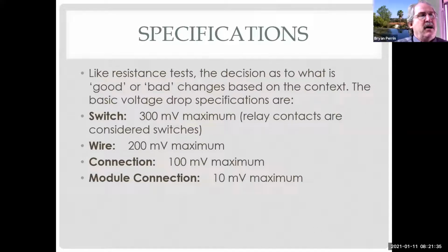But you can see it's not uncommon that, by the time I go through some connectors, go to my ignition switch and go down to my starter, I might lose 0.7 of a volt. Because, right, it's cumulative. I got wires, I got connectors, I got all these things. So even if I have an ignition switch that might be a little over, maybe my wires and connectors are under. So the total voltage that's getting there is what I would expect to get there. Therefore, it can't be my problem. So, if I have an ignition switch dropping 700 millivolts, that's definitely a problem because that shows me the switch is worn. And even if it's not the problem today, it's going to be a problem in the near future. So I'd want to let my customer know about that.